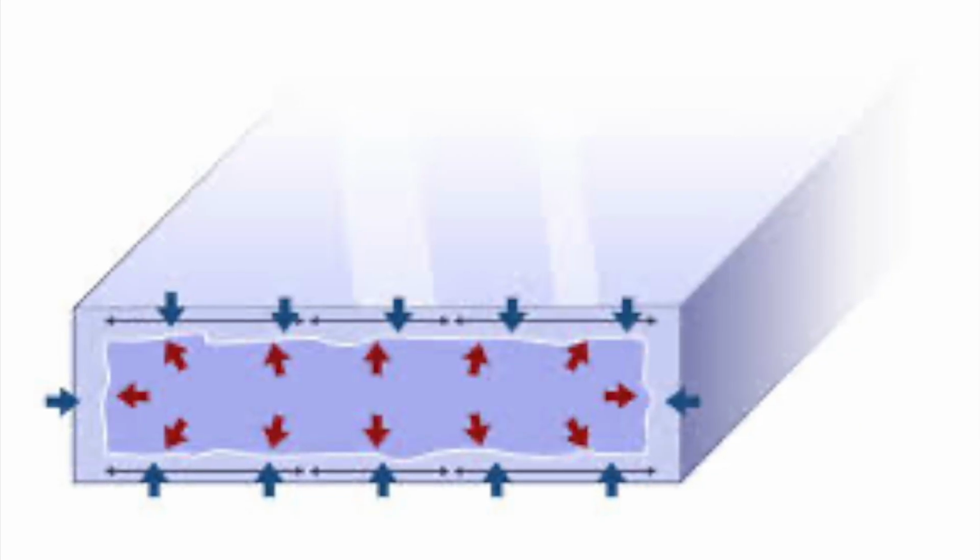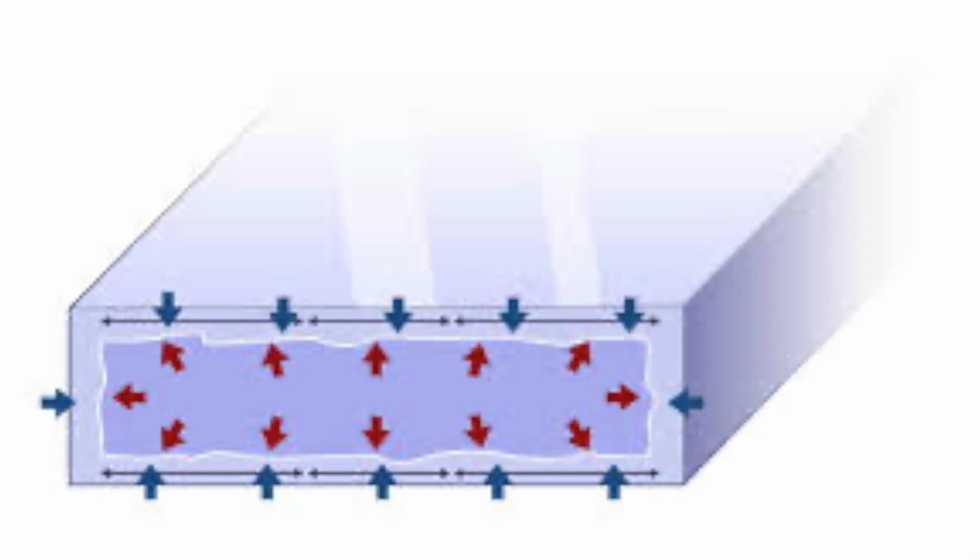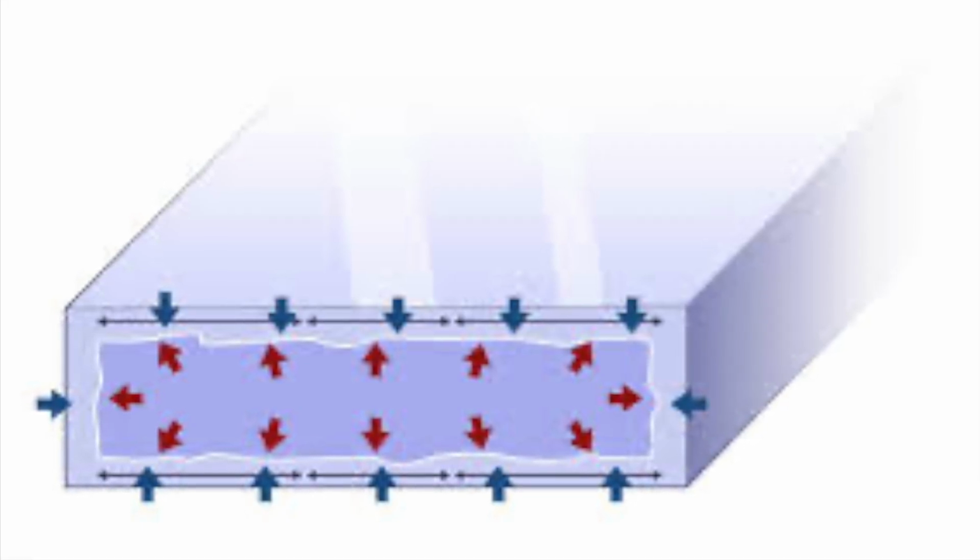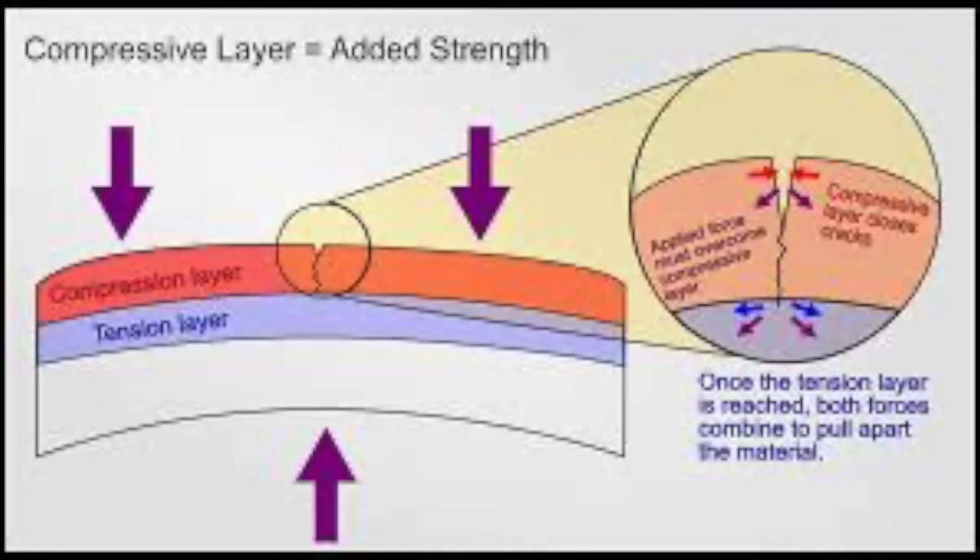But why is this effective? The reason tempering works is due to the internal forces within the glass. Once the glass is cooled, the center of the glass plane tries to pull back from the outer surfaces. This creates a state of tension in the center of the piece and a state of compression on the outer surface of the panel. The duality of forces invites the glass to shrink inward, which significantly increases its resistance, thus making it harder to shatter and a lot more resistant.